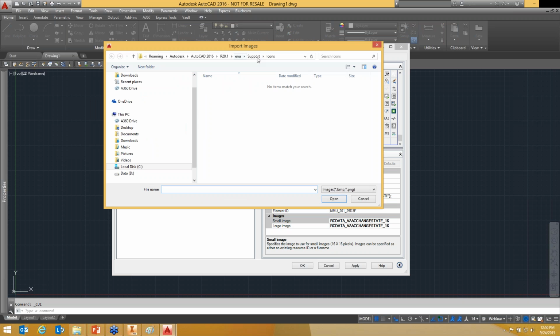And in this case, I can go into the folder where my image file is stored. In this case, I've got an ASCII logo bitmap sitting there. And I can bring that directly into the menu. Again, it's embedded in the menu file rather than being an external image file that I have to point to. If any of you have ever had problems when you're putting these things together and you're getting the clouds as your icon rather than the icon that you pointed to, the bitmap, this is one way you can get it embedded in. You can pass this menu around to everybody and then they will have this image.